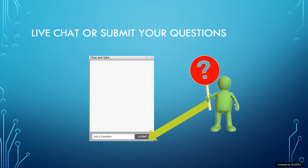This viewer has a question. What system is more costly to maintain, an oil-free compressor or a lubricated machine with food-grade oil? I think we touched a little bit on it. Okay, so the oil-free compressor, we said, costs more, and when I say costs more, it's quite a bit more. It could be more than 50%.